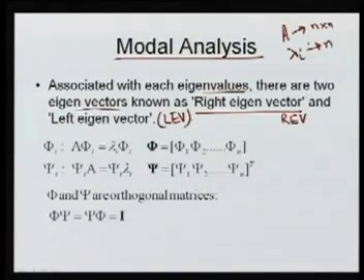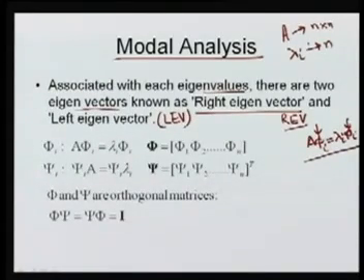So how can we get it? We know the state transition matrix A. If you go for the right eigenvector, using some vector phi that satisfies your eigenvalue equation for phi i, for all i. This phi is nothing but the right eigenvector, because it is on the right hand side, where we are multiplying this vector. Why is it a vector? Because phi will again have order n, from 1 to n.